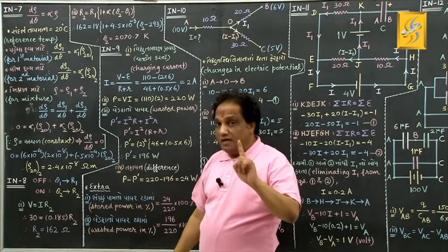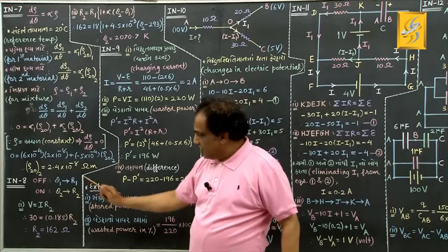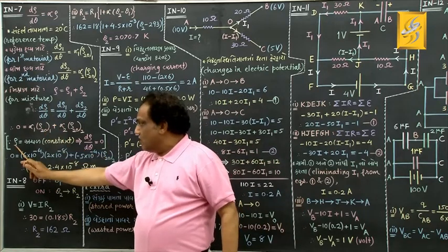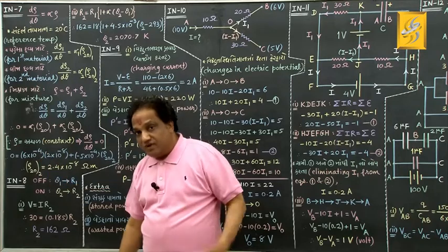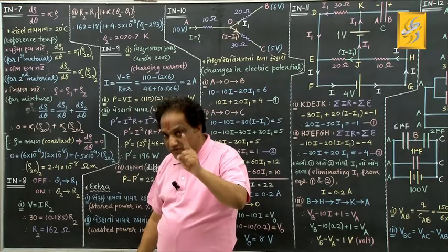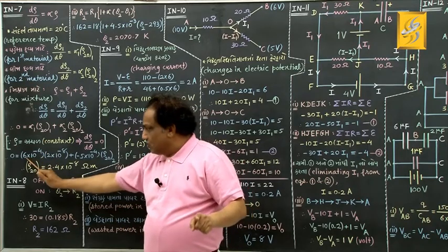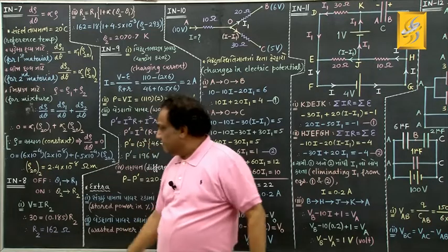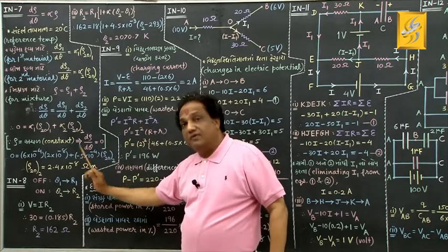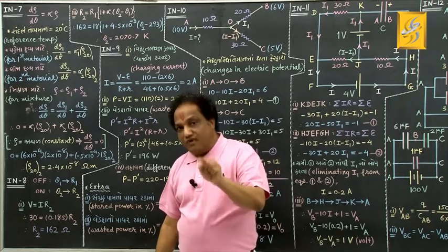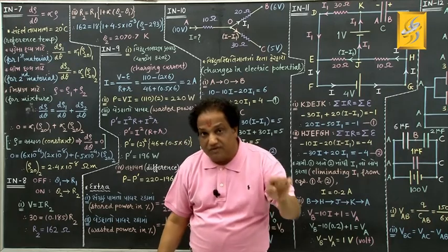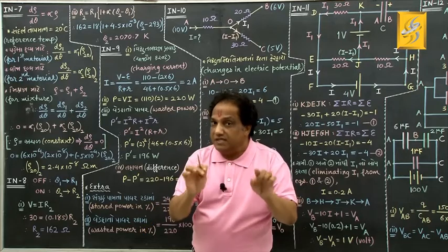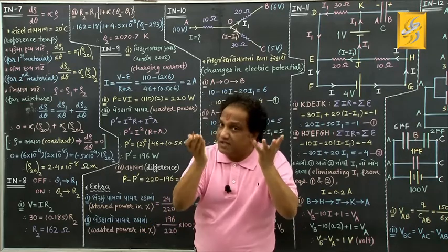And can you understand one point here? Why has the resistivity of the mixture remained constant? What is the reason? The reason is, have you seen, the temperature coefficient of resistivity for the first material is positive and for the second material it is negative. So, what does it mean? For the first material, when the temperature coefficient of resistivity is positive, meaning if temperature increases, then the resistivity of the first material will increase.